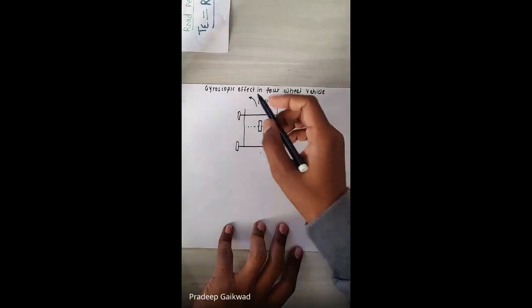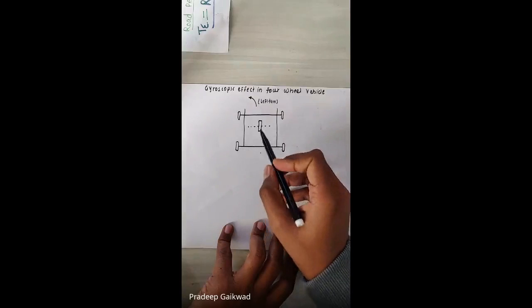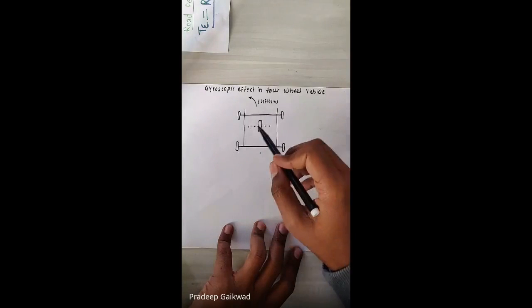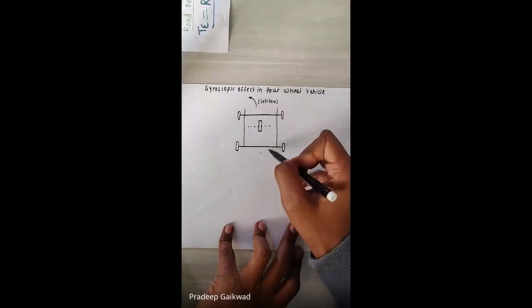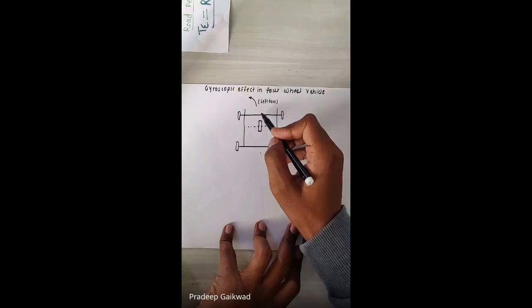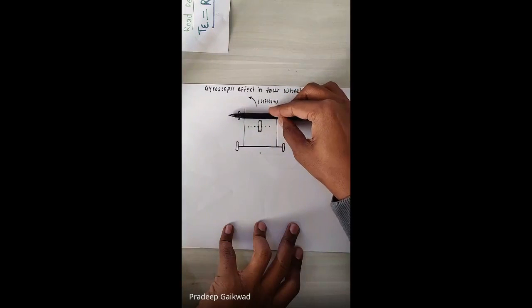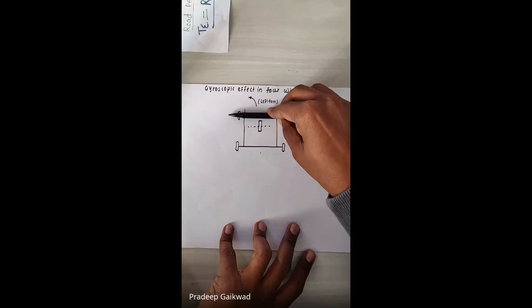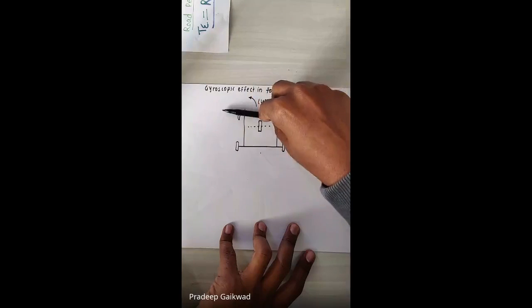So here, let's say this is the front axle, this one is the rear axle, and this one is the engine. I have shown you the rotating parts in a four-wheel vehicle. As there are rotating parts like wheels and engine, there will be a gyroscopic effect when it takes a left turn or right turn. Let's say this is your initial position of the axis. What happens when it is taking a left turn? It may move like this. So there is precession of the spin axis.